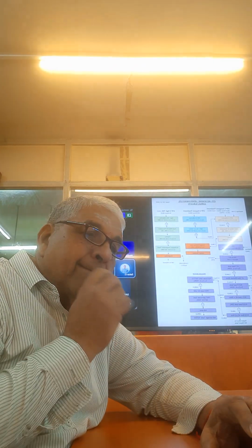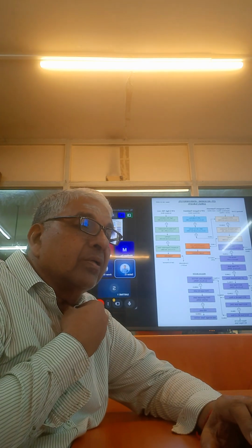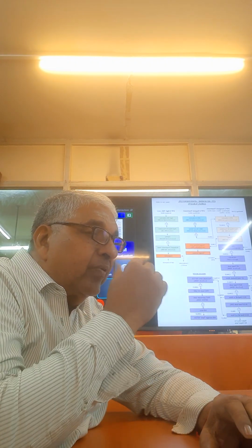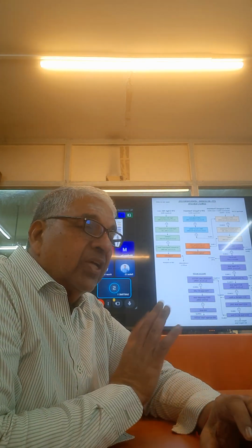Okay, and you were saying if we are going for a 3-stage RO, the final reject can be directly sent outside. What did you actually mean? We add one more stage RO? Yeah, what I have given you here is 2-stage RO. With 2-stage RO, you can get 90 to 95 percent plus anywhere, because the last few percentages will be fluctuating.